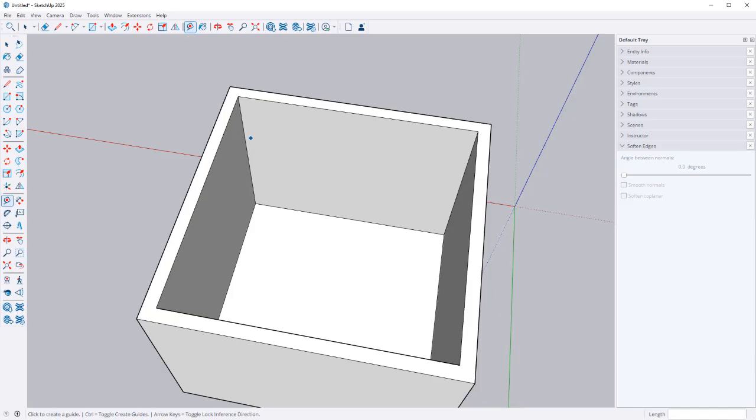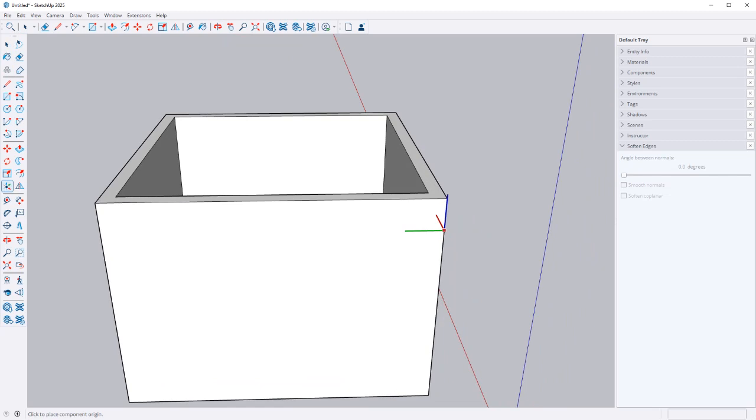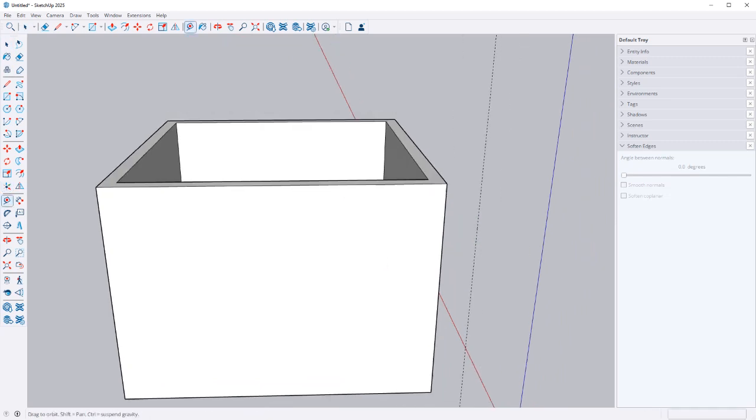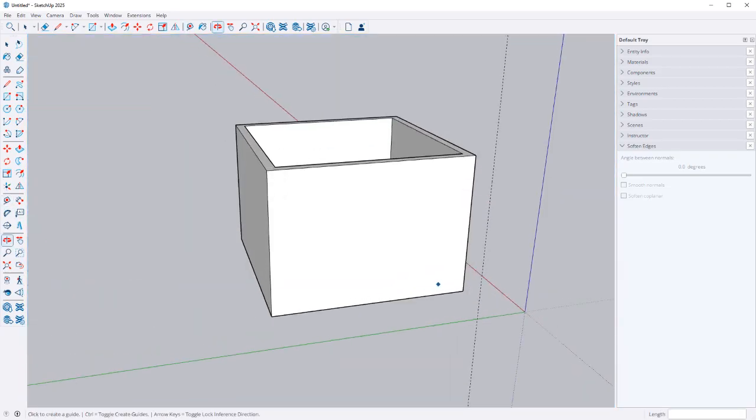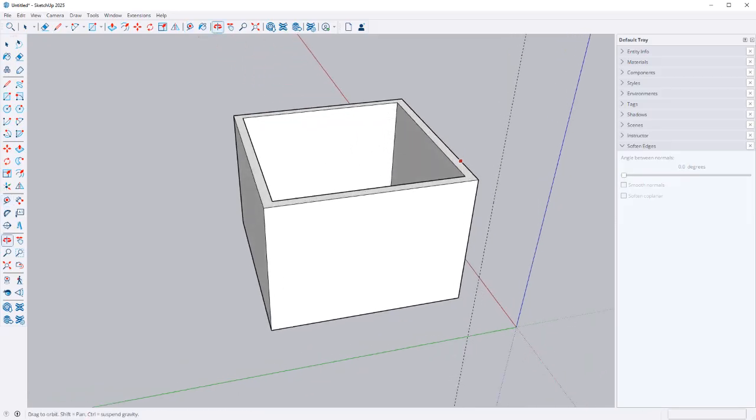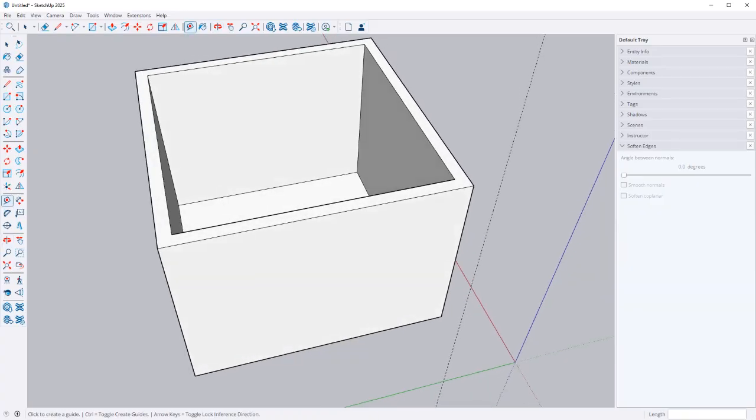The tape measure works best when you reference an edge like this. See how when I'm hovering over here, it says I'm on edge. If I go here, it says I'm on endpoint. And what you end up with, if you're on the edge, is it's going to draw a line off into infinity. You can see it goes way up there, completely parallel to whatever this line was. Because this line was parallel to the blue axis, it's going to go off into the blue axis forever.